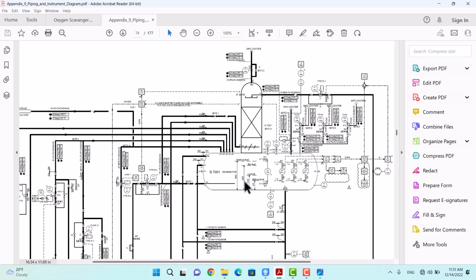So it serves two purposes. At first, it heats up some of the water around itself, and also it travels to the upper part of the deaerator where it comes in contact with the DM water, which is showered from above. In the packing sections, the LP steam is contacted with the DM water showered from above, and the LP steam helps remove the oxygen from the DM water in these sections.